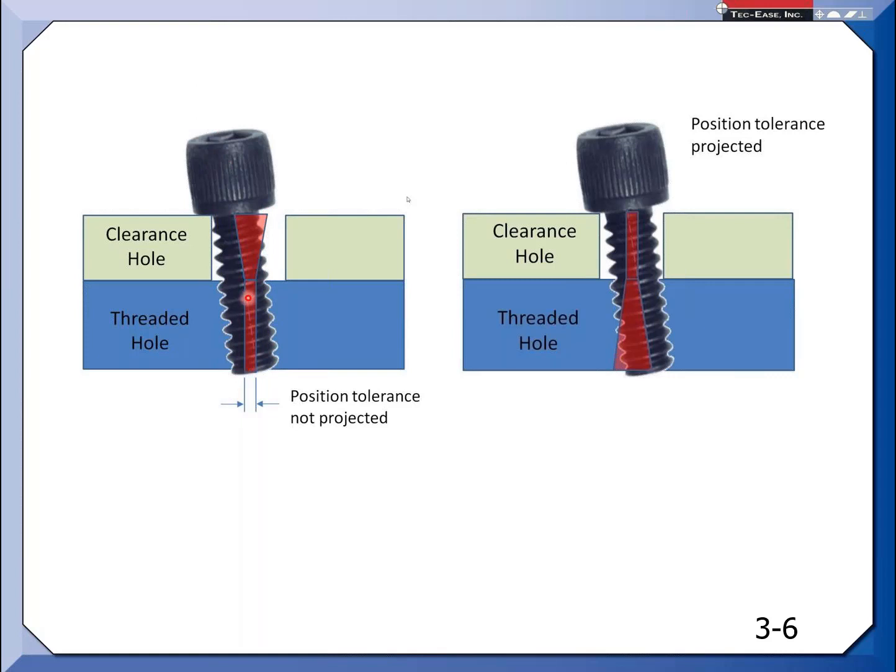I have, sorry to say. I'm threading in my fastener. I can feel my bolt start to thread and then it stops. What's happening is I got it to start, but because the actual tapped hole is tilting, as my bolt goes in, I'm going to start cross-threading and doing damage between my bolt and my threaded hole, because my clearance hole is limiting how much tilt it can do. It may not compensate.